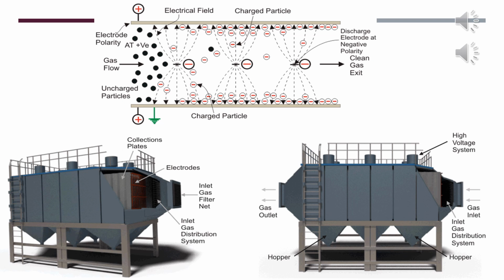As soon as the flue gases enter into the electrostatic precipitator, dust particles in the gases collide with the free electrons available in the medium between the electrodes, and the free electrons will be attached to the dust particles. As a result, the dust particles become negatively charged. Then these negatively charged particles will be attracted due to electrostatic force to the positive plates. Consequently, the charged dust particles move towards the positive plates and get deposited on them. Here, the extra electron from the dust particles will be removed on positive plates, and the particles then fall due to gravitational force. We call the positive plates as collecting plates.